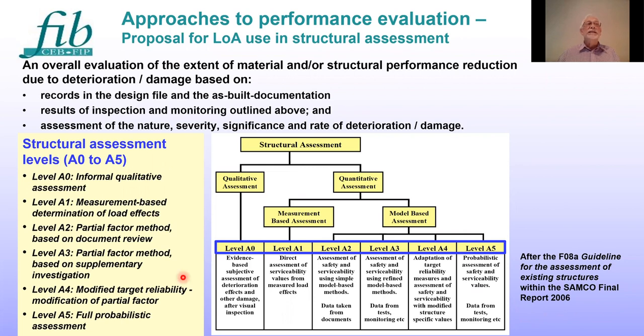It defines 6 levels of approximation, level 0, A0 through to A5, and it recognizes aspects such as whether it's a qualitative assessment or a quantitative assessment, and whether it's a measurement-based assessment or a model-based assessment, and you end up with a significant range of approaches for estimating the strength of the structure.